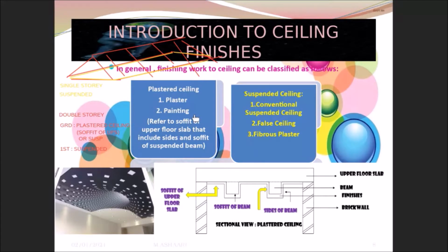For the plastered ceiling, because this is normally a component made from concrete, you cannot paint directly. You need to measure plaster and painting. Once you measure for the plaster, you can take quantity for painting. So I put here TQ, take quantity. Okay, Daniel. So this is the overview.